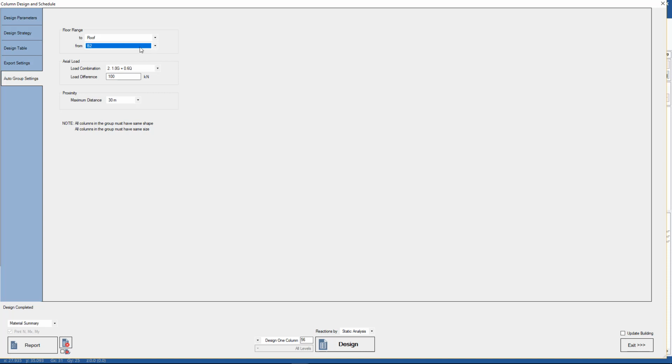Now, be careful when using this. If it's a larger job and you have groups present already, this may produce some undesirable results. Ideally this should be used on a blank design without any column groups so that no information gets lost, because this may produce many column groups. We're not going to use it in this case.